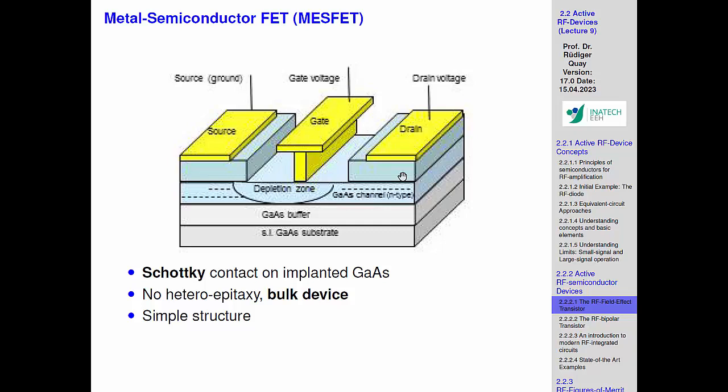So the initial Wi-Fi devices were, nobody had a good microwave FET, but they had gallium arsenide and they just needed 5 gigahertz. You know, from the beginning, Wi-Fi was at 2.4 and at 5 gigahertz. And they just did it. And what you learn from that is that the complexity of making this device is relatively low. So you have that particular wafer, you implant, put some metals, that's it. It's not cheap because, as you know, a Wi-Fi adapter cannot cost a fortune.